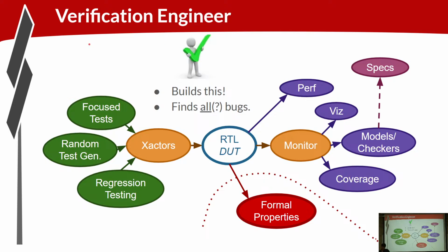The verification world is a bit more complex than the RTL world. Verification tends to deal with a myriad of languages, different tools, environments, ways of approaching a problem. So in general terms, the verification engineer is creating the test bench. That's everything surrounding the RTL. That includes transactors that are driving stimulus into the RTL. So the tests define what that stimulus needs to be in some way. For the CPUs that you designed, that would be a test program. The transactor is responsible for applying that test program to the model.